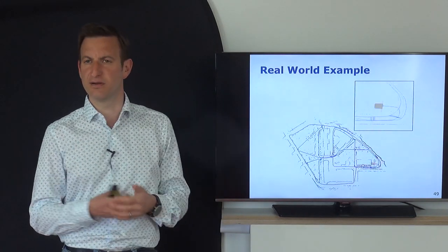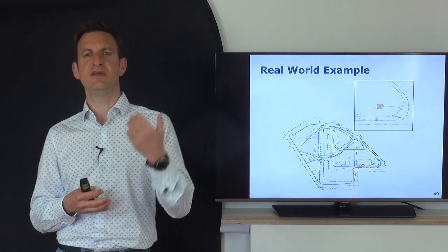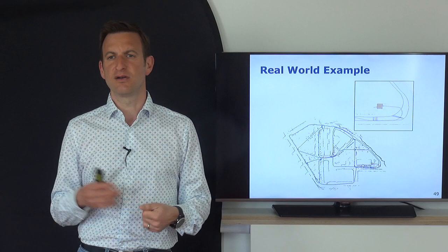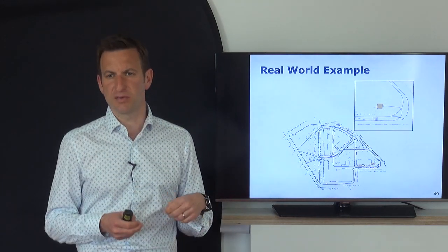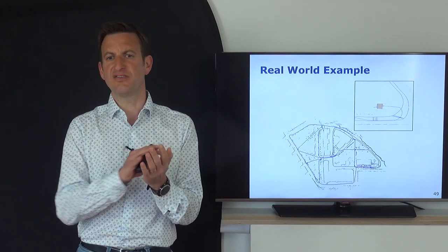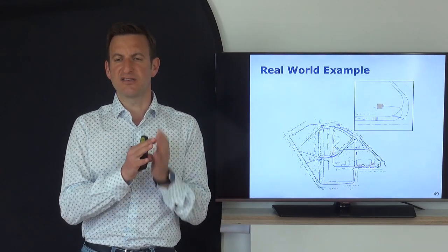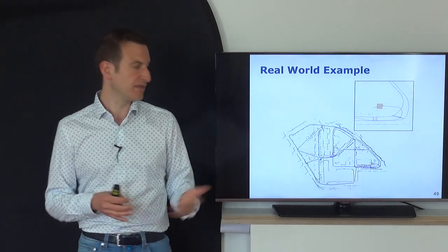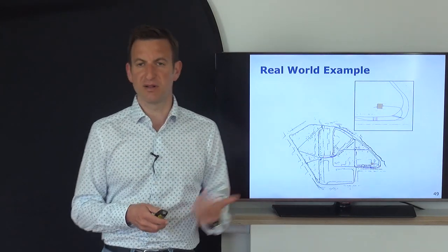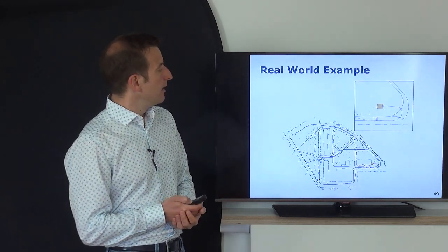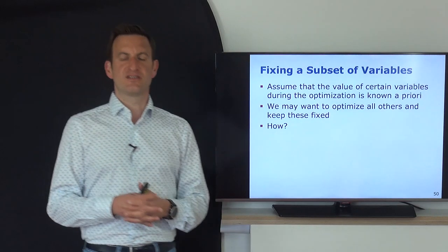This is a result of a full SLAM system which runs ICP, registers one scan against the next scan, builds up a graph, and also looks for loop closures. Whenever the robot is close to a place it has been before, there's an ICP running to see whether we find a good match. If so, we add loop closure constraints. And then you can build a simple laser-based SLAM system like that. This was the basics of this approach.